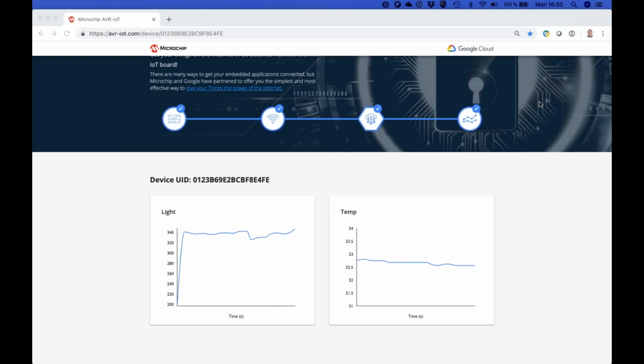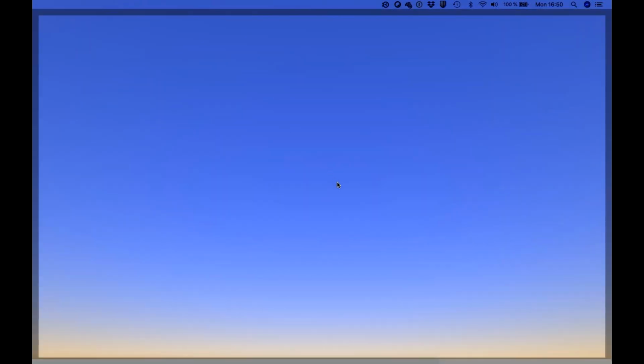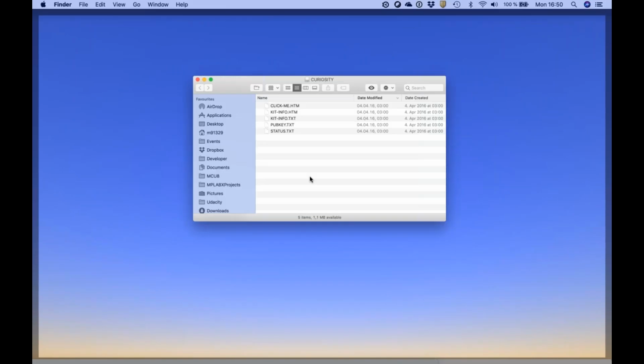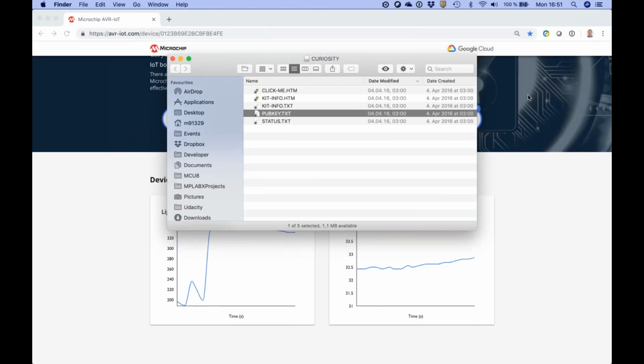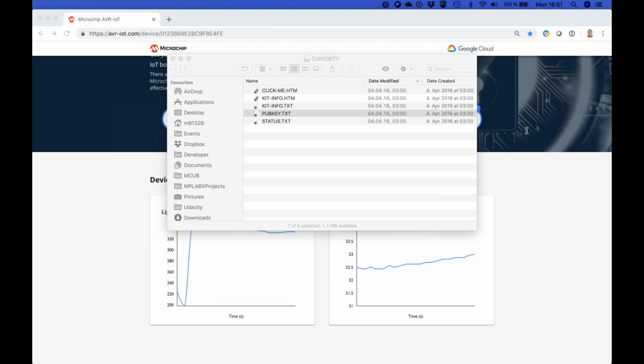Great questions. I already used the Google Cloud. So what to do in Google Cloud to set this up? Simple. You enable your IoT Core service, and then you create a registry, and then you go to the device, and you ask for the public key from your device, and you add it to your registry. How do you ask for the public key? As I showed you, the hard drive, you open it, the public key is this file. Copy that file into your registry, and voila, your board is now inside your existing Google Cloud account, and you can start playing with it immediately.